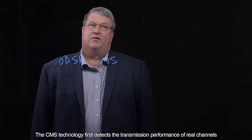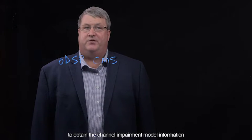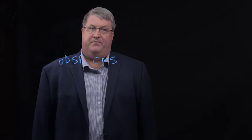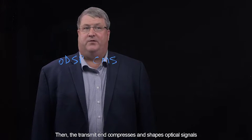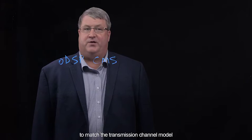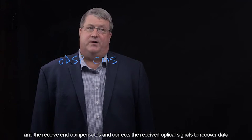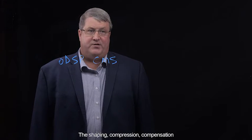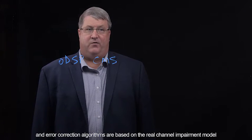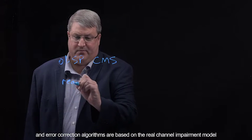The CMS technology first detects the transmission performance of real channels to obtain the channel impairment model information. Then the transmit end compresses and shapes optical signals to match the transmission channel model, and the receive end compensates and corrects the received optical signals to recover data. The shaping, compression, compensation, and error correction algorithms are based on the real channel impairment model.